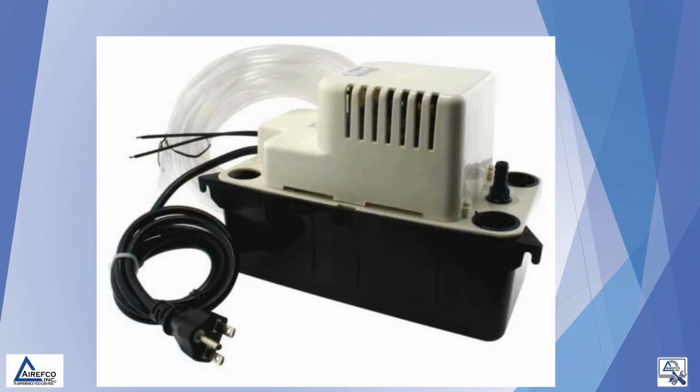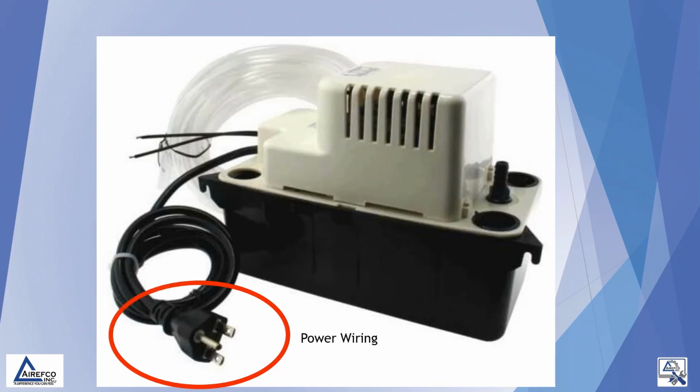So on most condensate pumps, there are two different connections you need to make. The first one would be the power connection. Normally, condensate pumps are usually plugged into an outlet that is either mounted on the furnace or near the furnace. But this needs to be a constant power supply that is never interrupted. The second connection that is made is the safety switch on the condensate pump, so that if the float or the condensate pump itself fails, it will shut down the condensing furnace and will not allow condensation to keep building up, which could overflow and do damage to the home.